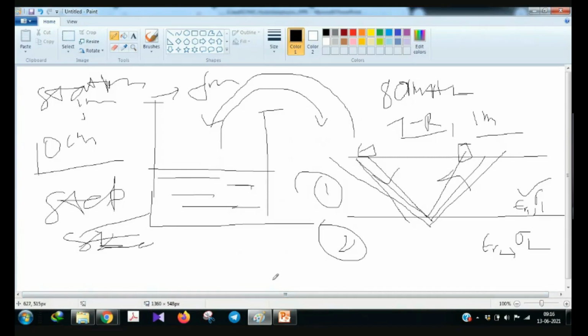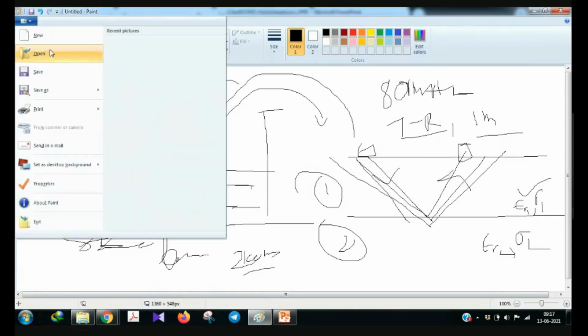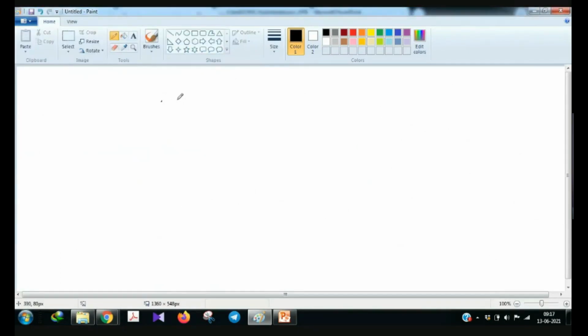Suppose you don't have much time and you have to cover a whole lot of area, then you will go for a larger step size. If you take 20 centimeters instead of 10 centimeters, then it might not give you as good a result, because of closer spacing, it's a simple concept. If you take data at close spacing, that can help you to draw. Suppose you have to draw this thing, and you have taken closely spaced data, then you can draw like this, connecting the dots.